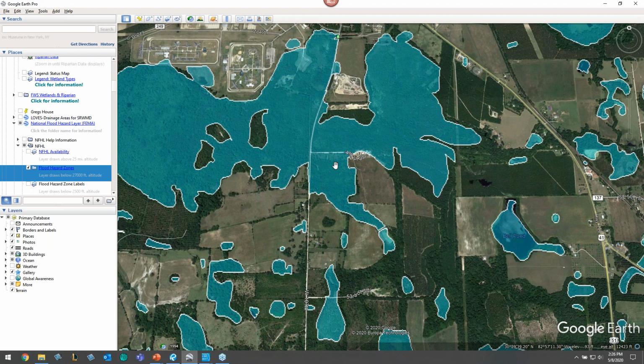The key thing with these ponds, for those who've never done it, and I'm going off on a tangent here, is the pond cannot go below the seasonal high water table. Obviously, it makes no sense, because if you're going below the seasonal high water table, then you're not compensating. These ponds are usually pretty shallow, a foot, 2 foot. I shouldn't say that, it depends on your soil type and where you are in the state of Florida.